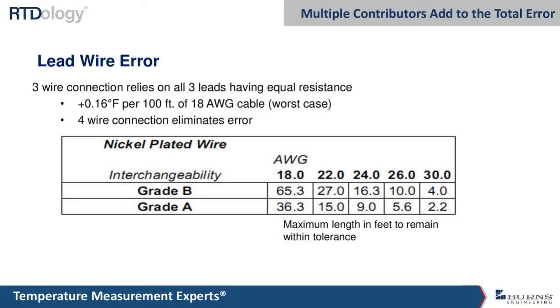But the bottom line is that yes, you do need more immersion to overcome stem conduction in any kind of air, whatever kind of gas you may be measuring. It does make a difference. It's really hard to make a good estimate of what is needed. In the room air temp case, it was just, let's get a really long probe and we know it'll work. I just don't know exactly where that cutoff point is. So anyway, we'll move on.